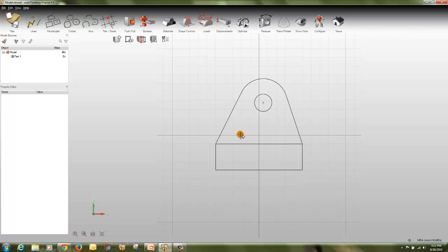Also, let's create one more like this. So now if you select these two and activate the parallel constraints, so this will be parallel, as you can see. Similarly, these two, if you want it parallel, so this will also become parallel. It automatically shifts. You can see that. So these are the parallels.